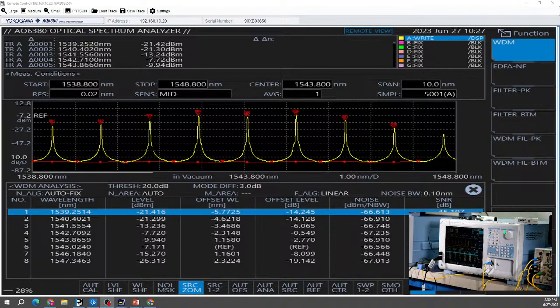What are the calibration options offered with the 6380 certificate of conformance? As far as the calibration certificates, we offer NIST traceable calibration. Everything is tied to the NIST standards for that certificate. It's an option. The unit comes with a test certificate with the calibration data from the factory, but some customers need the NIST for US-based regulatory reasons, and we can provide it as an option. You request it when you order the unit.